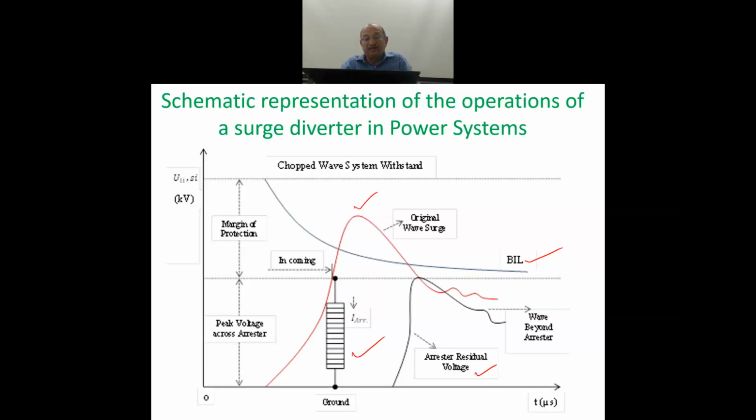that when we design the insulation system, which is the base of the power system, we do take into consideration how much basic insulation should be provided so that the system is able to not only withstand the rated power frequency voltage continuously, but also the impulse voltages or the overvoltages faced by the system due to lightning strikes, due to the switching operations, etc. Also, all this is designed taking into consideration the level and working of the protective devices which protect the system from the peak value of the overvoltage.